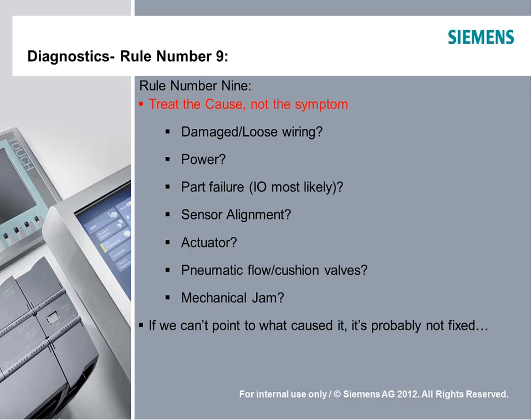Effectively, if you've got one 40-amp, 24-volt DC power supply running the whole machine, there are components we can add to that system to make it a lot more resistant to complete shutdown. Siemens makes a nice little module that goes downstream of a big power supply and divides that high-current supply into, let's say, four different 10-amp circuits, so that we can isolate the individual circuits and not lose the whole machine.